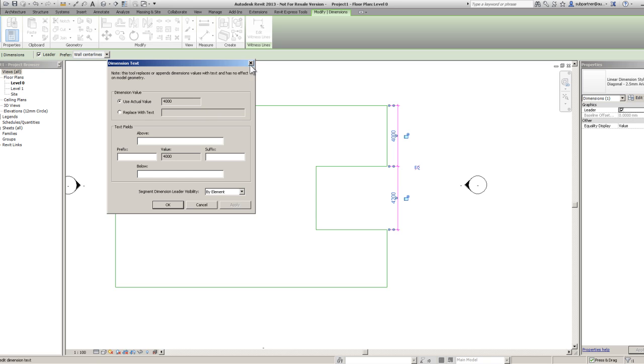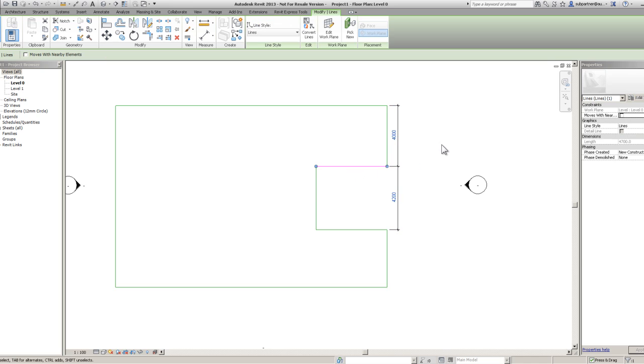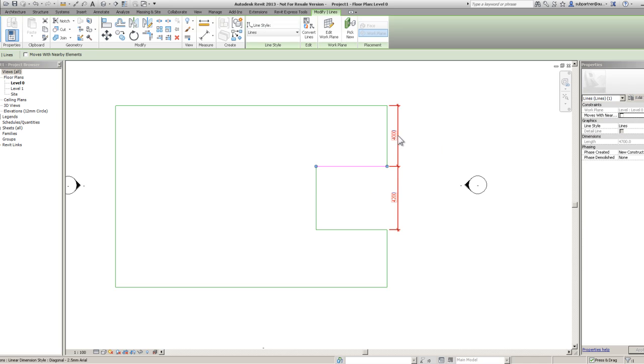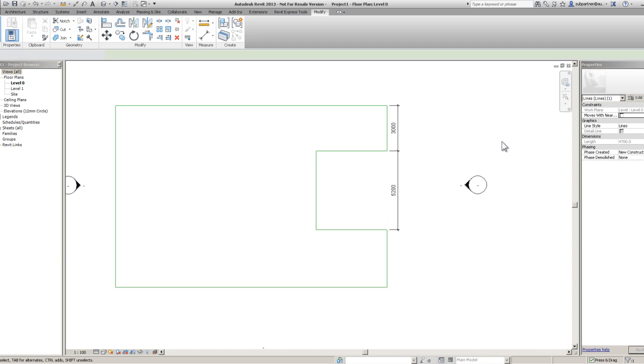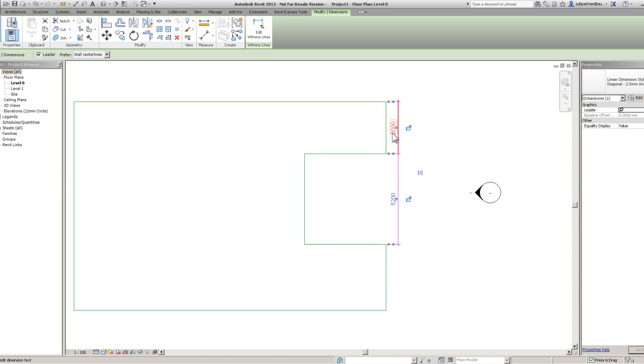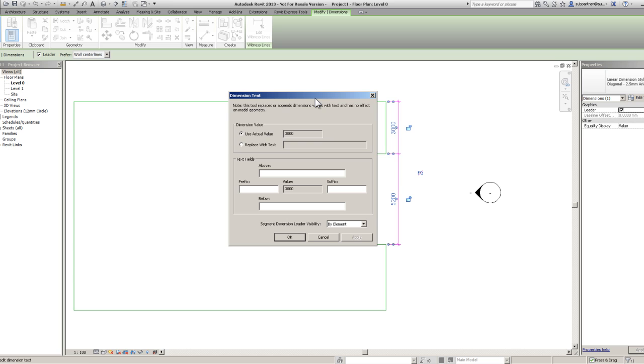What's that box? Panic. Now basically what's happening is, that's a different mode, we'll come to that in a second. To move that line, you still have to select that line. Just watch what happens when I select it. Select that line, and you can see how the dimension's actual text input has gone blue. It means you can pick the dimension, say 3 meters, done. Doing it the other way round, highlighting the dimension and then picking the box there, is basically our dimension text editor.